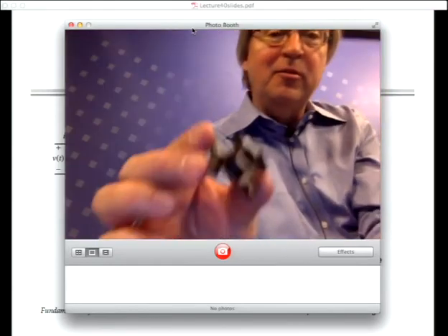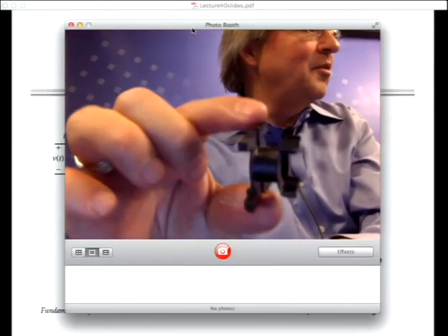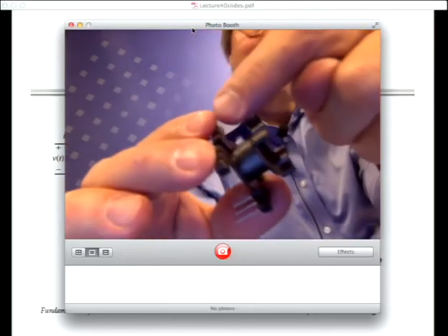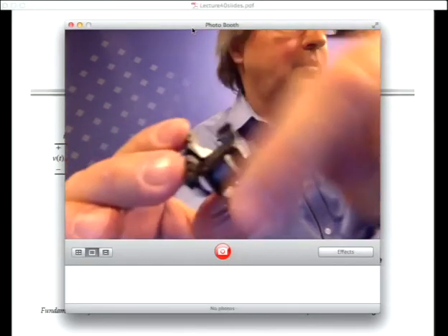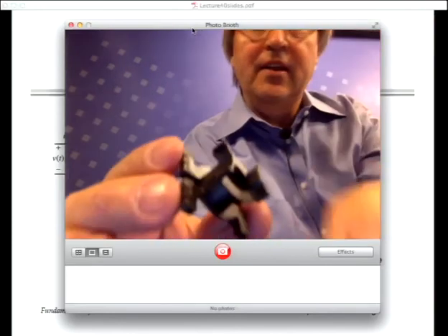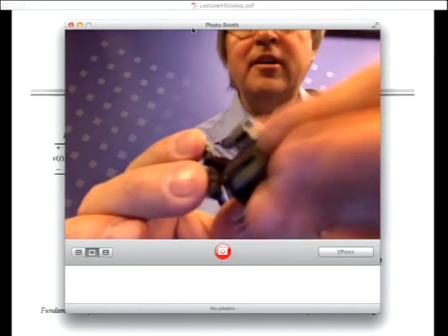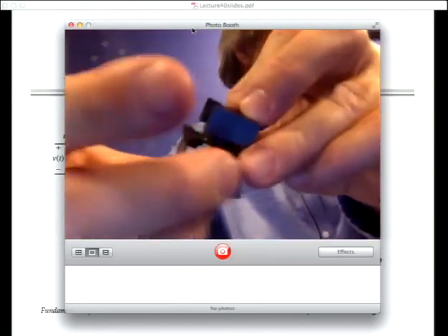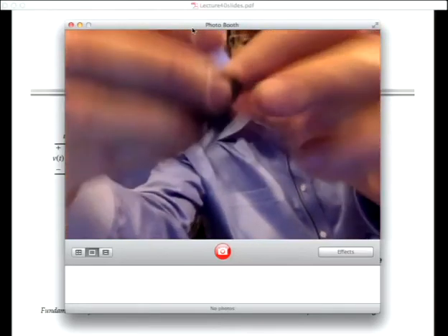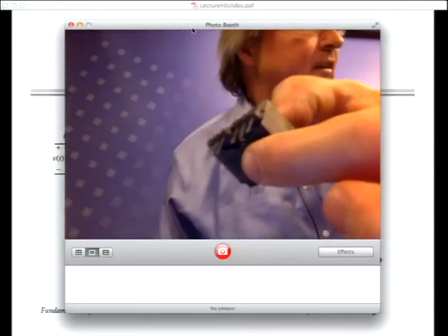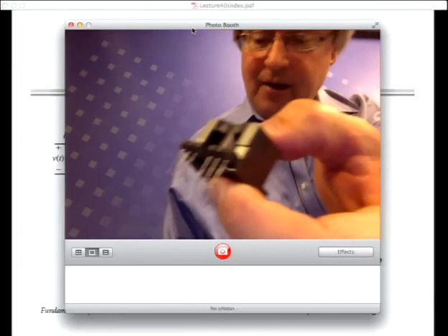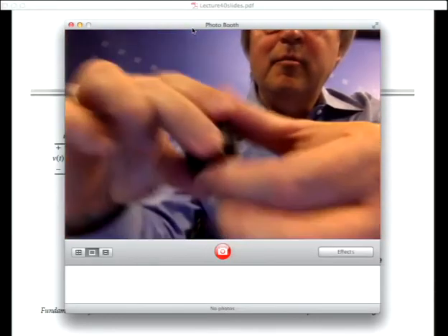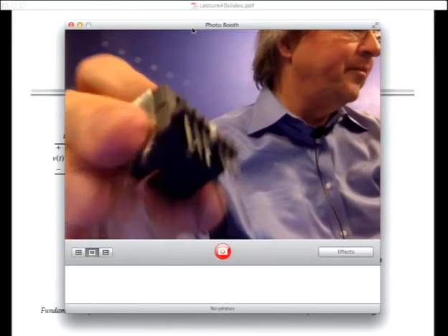So it comes with a plastic bobbin, and you're supposed to wind your wire on this bobbin around like this. And then you put the core over it. And you clamp it together, and it plugs into your printed circuit board.